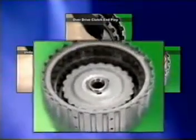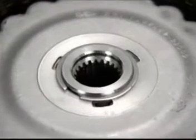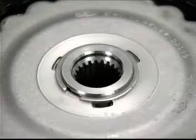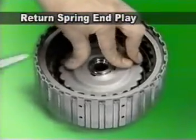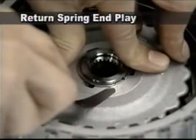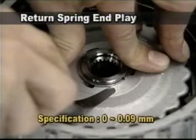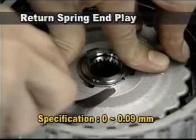As for the reverse clutch and overdrive clutch, end play of the return spring should be measured and adjusted in addition to the disc and plate. Measure the gap between the snap ring and retainer with the thickness gauge by pressing the return spring retainer with approximately 5 kilogram force by hand. If the measured value exceeds the specification, change the snap ring with one of the 4 different snap rings in thickness.